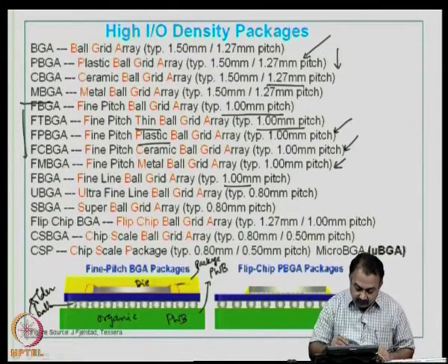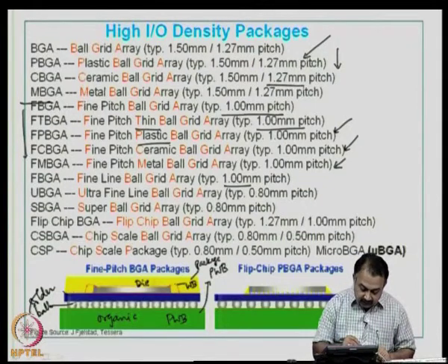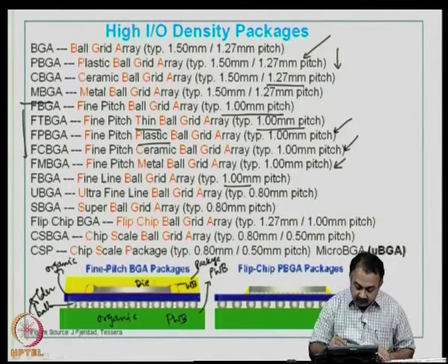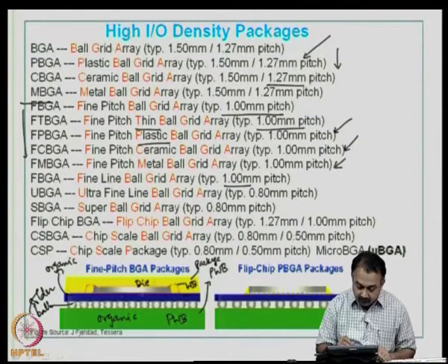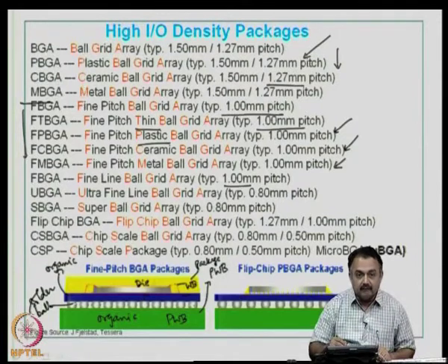Then you can see here a typical wire bond, let us say, and then in between the die and this blue area that you see here is an adhesive which attaches the die, and this is again an organic substrate. This organic substrate is typically about 4 to 8 layers of construction. As I mentioned before, the IOs of the die are fanned out through this entire 4 layer or 6 layer or 8 layer substrate to terminate in a solder ball.